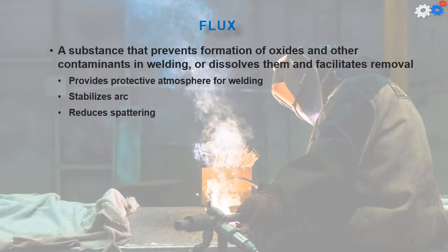The flux is a substance that prevents the formation of oxides and other contaminants in the welding, or dissolves them and facilitates their removal. The flux provides a protective atmosphere for the welding, stabilizes the arc, and reduces spattering.